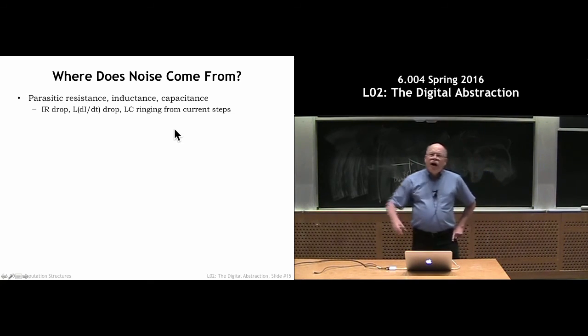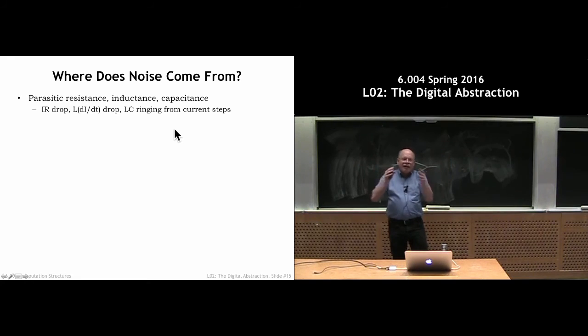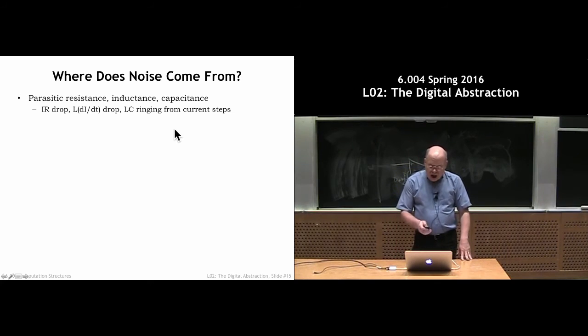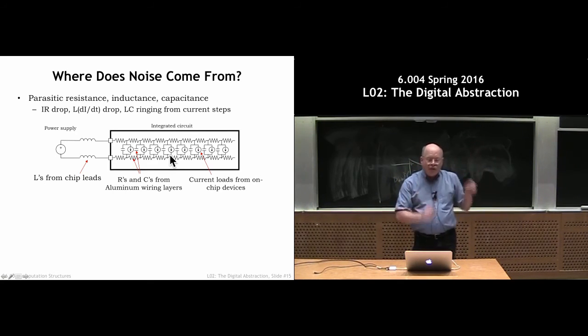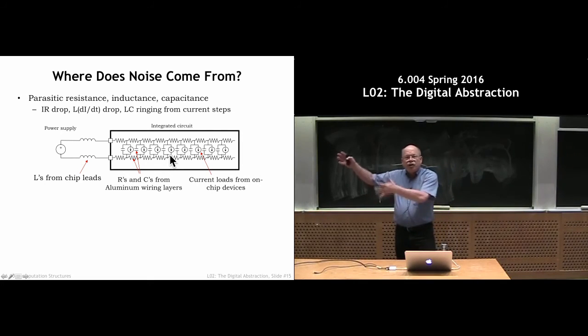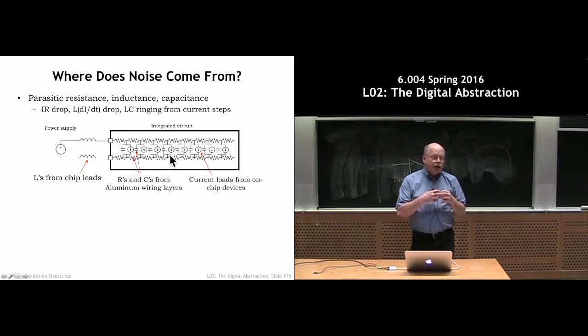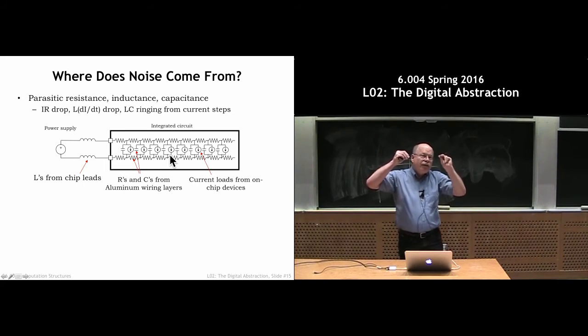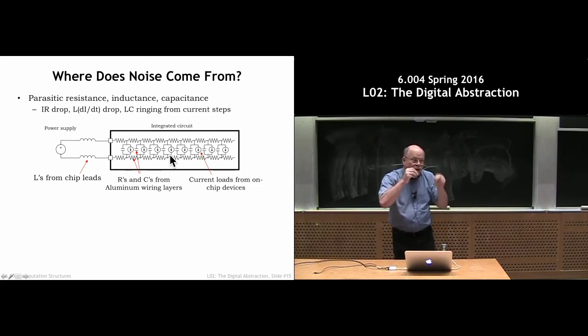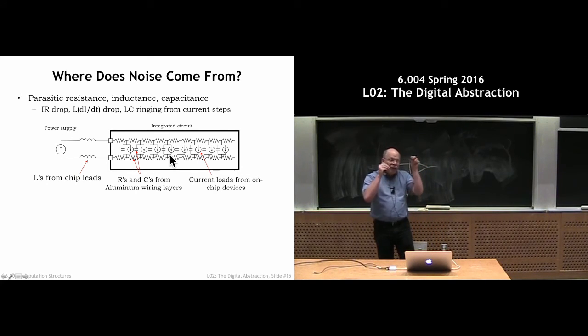First of all, you might be thinking of cosmic rays and thunderbolts. The answer, unfortunately, is that most of the noise we're worried about comes from the operation of the circuit itself. If you're switching currents on and off, with little digital switches opening and closing to perform logic functions and routing voltages and currents around, that itself will produce small variations in voltages. For example, you run current through a wire. The wires have very low resistance, but not zero resistance, so there is some very small voltage drop across every conductor.